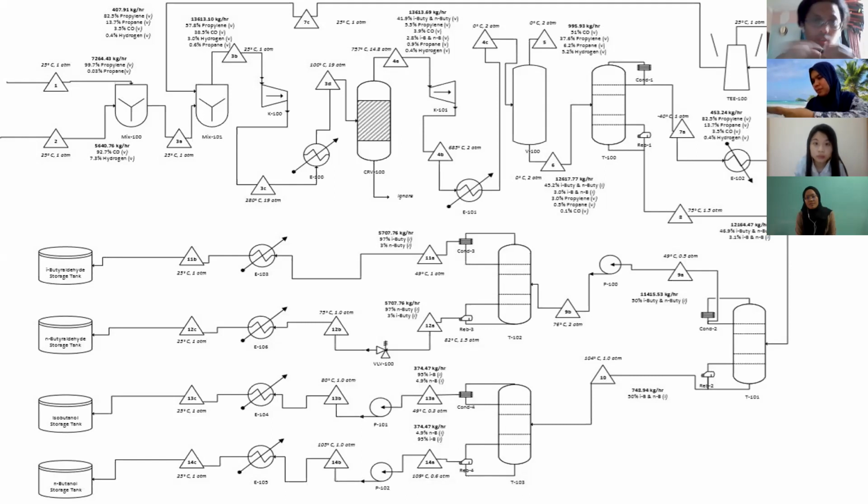Okay. Any more comments or questions? I have your distillation column that is operating at minus 40. Which distillation column? This one, 7A. That distillate, why minus 40? Doctor, that one is the distillate of the first distillation column. The distillate stream. Oh, so your distillation operating condition is? 0 degrees C at stream 6. Okay, also using 0 degrees C. Yes, the same condition as the flash drum.